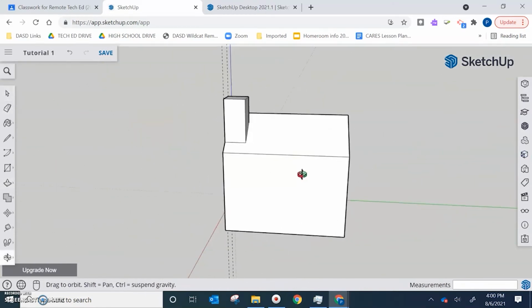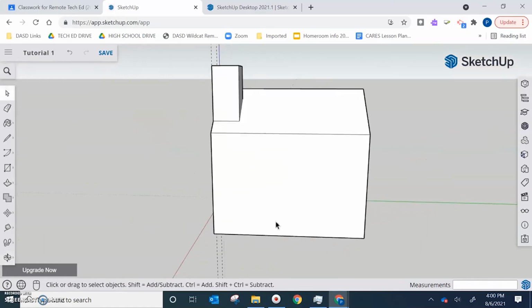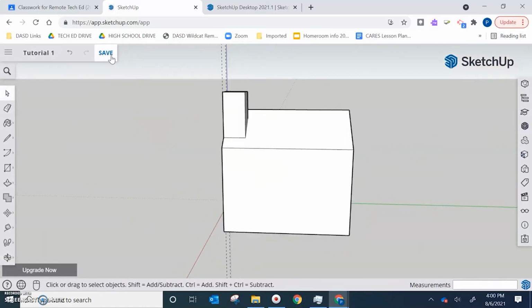So now on the front of the house, we're going to put a little door on here. I'm going to save my work here. Let's put a little door. Again, let's use my guidelines first. So let's just come over to the midpoint. Then off of the midpoint, I'm going to click and drag. Let's just go 1 foot off of each side.